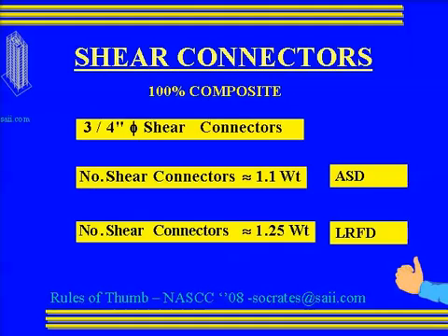It's an interesting phenomenon. When we went to LRFD, what we found out early, and what sold LRFD to most engineers in the first place, is that you came up with approximately 1 size smaller for composite beams than what you used to do in ASD, just by looking at the ultimate. But interestingly enough, the number of studs required to develop the same moment was essentially the same.